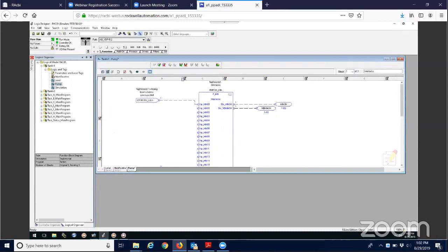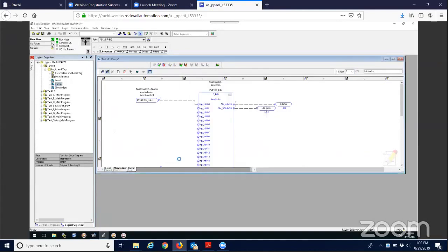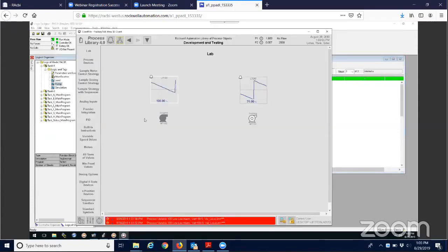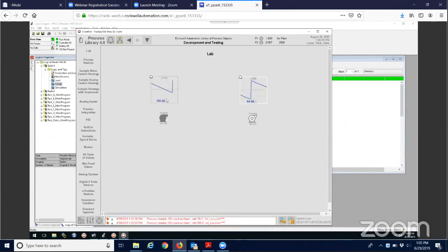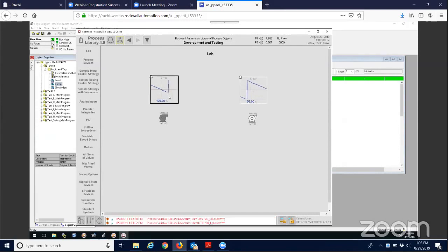Okay, so I'm good. I accept that edit. I say, okay, let's roll with that. I like it. I'm changing the pump. Good, now I've made my change. I know I'm green. So now I'm going to go back to the runtime and say, wow, what happened? I stopped. I went down. While I was making that change, I was in alarm mode, and I created that interlock, and it stopped me in the middle of everything.